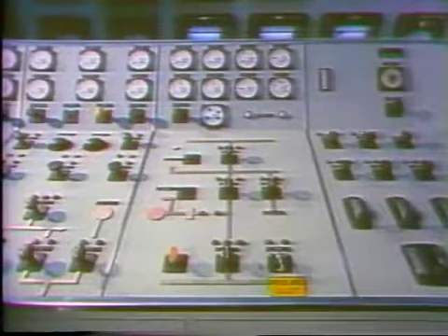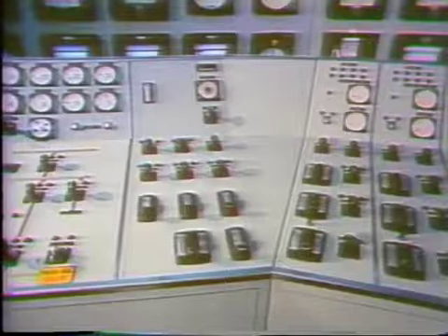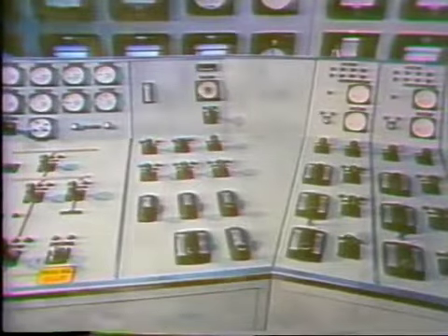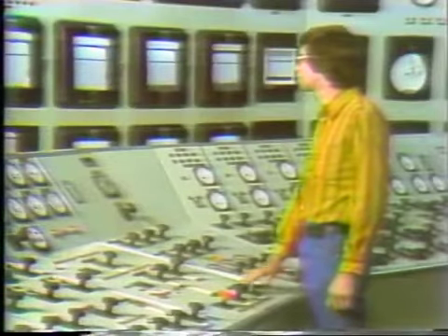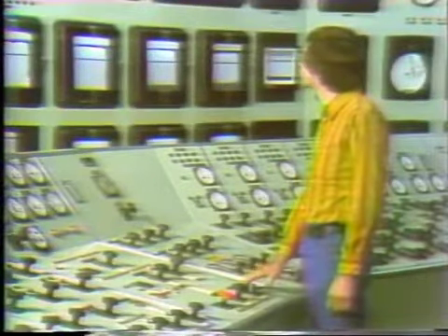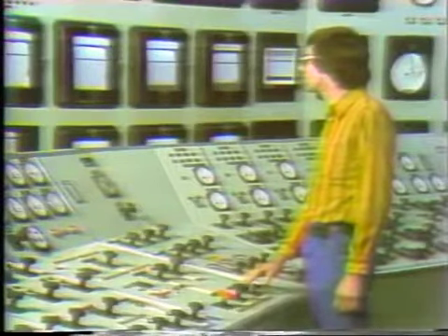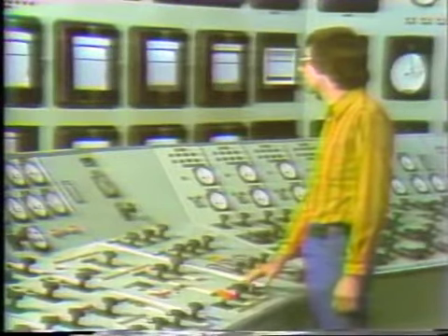Now, keep in mind that there isn't a single controller that does everything. There are usually separate control systems for the turbine, feed water, fuel, and combustion air. Of course, control systems vary from plant to plant, and you'll need to learn exactly how yours is arranged. But what generally happens is that the operator changes load on the turbine, and the rest of the systems automatically adjust accordingly.